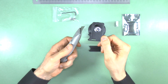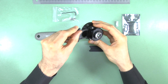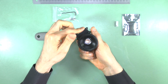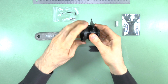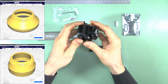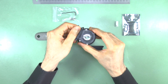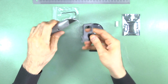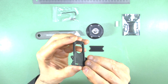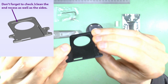First, clean up the printed parts and test the SLM holder to see if it fits easily and with minimum force into the slots you intend to use it with. Here I'm using an Abe condenser. Ensure that the adapter module is attached to the condenser during the test, either the condenser to mirror holder adapter or the condenser to upper collector adapter. If there is difficulty inserting or removing the SLM holder, scrape and/or do whatever else it takes to fix the problem at this stage before inserting the delicate TFT screen. Ensure that the slot that will accept the TFT panel is clear of any stray plastic blebs or threads.